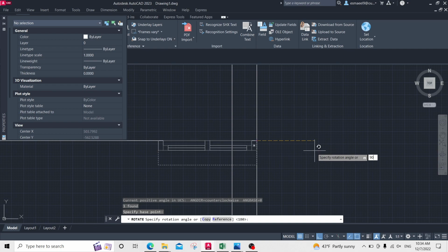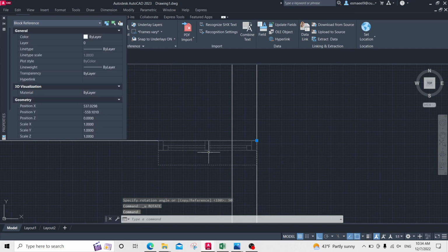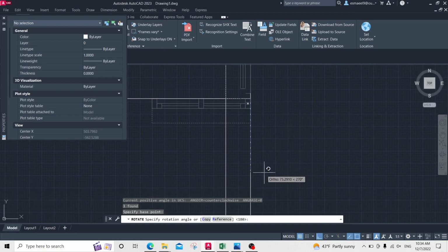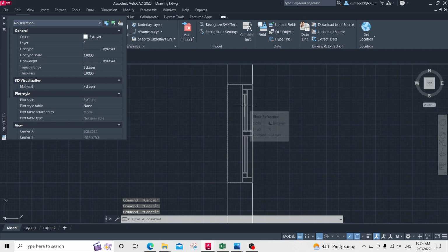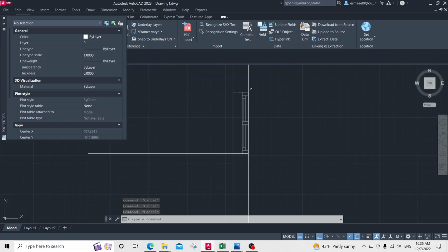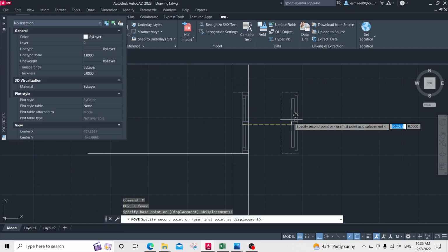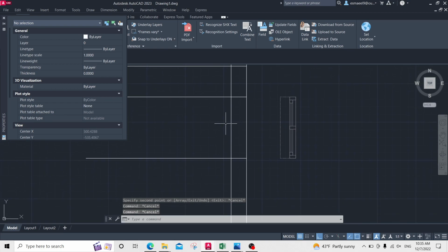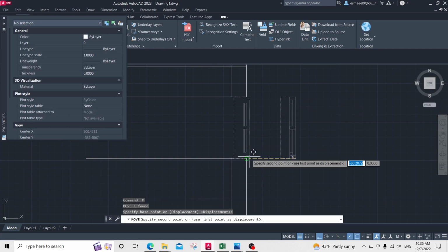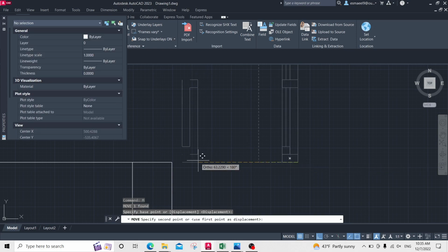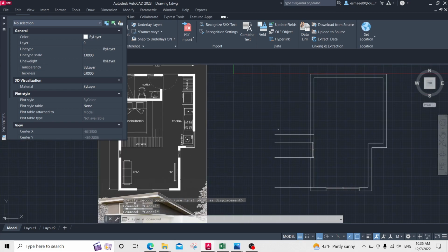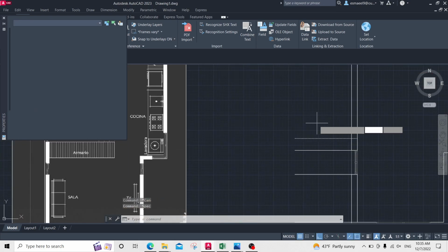Now I will select this corner, the same corner. Why? Because I will just rotate it, not 90. Let me just RO this one like this. It's already rotated. The same issue happened with us. I didn't even delete the other lines, so I will move it back. CO 100, and then TR, move it into this point. And now it's not exactly like this, but let me move this one again,